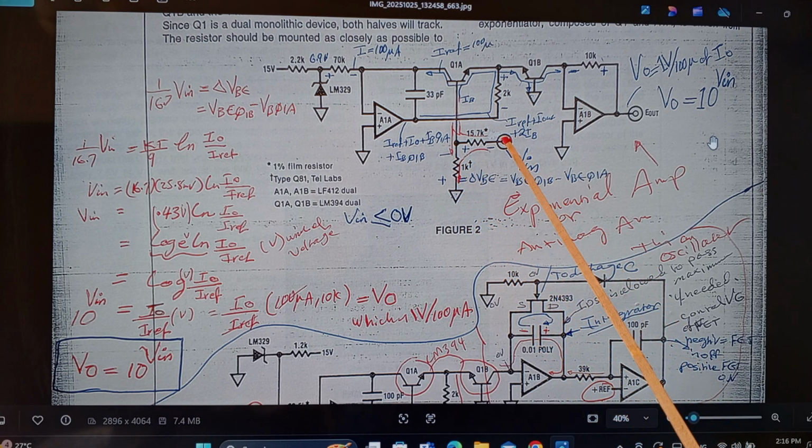And by the way, that voltage has to be negative, can't be positive. So we are applying minus 1 volt in here. So you get your minus and plus as the polarities indicate, which is minus 60 millivolts. And what does that mean? Applying 60 millivolts to the base of this transistor in here means you get your VBE equal to whatever VBE is caused by the 100 microamps, pulled down by a further 60 millivolts.